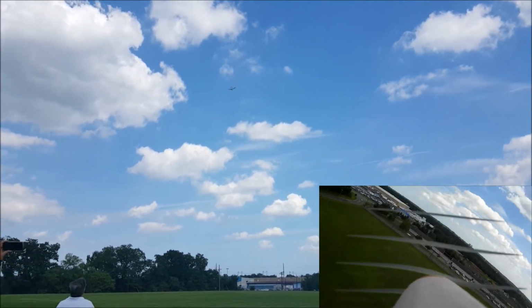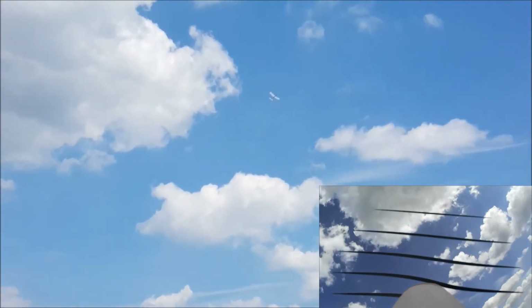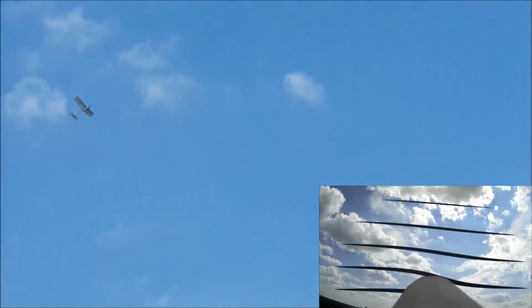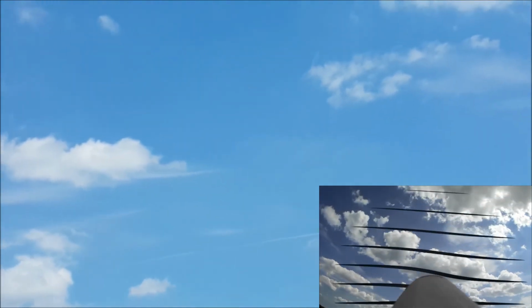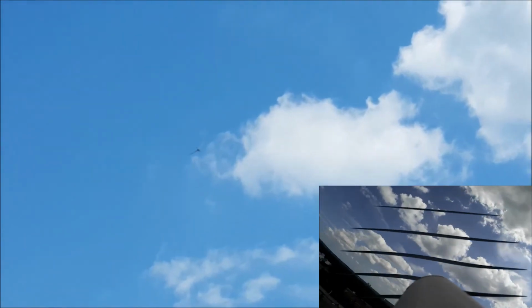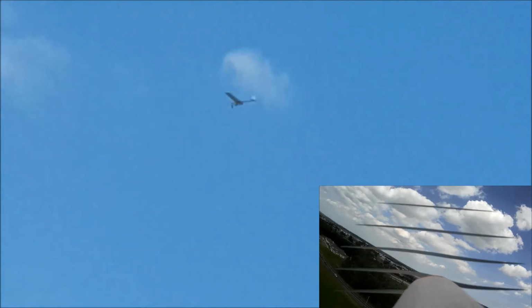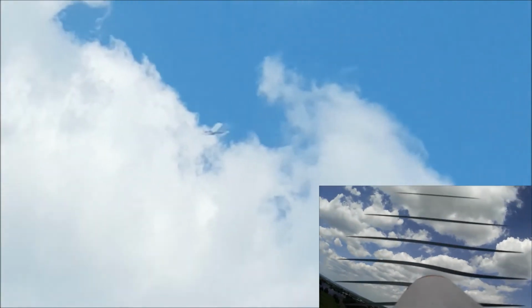Right there you see the plane kind of hover in the air. That's because due to the low wing loading of our plane, we had a very low minimum airspeed. And when the airspeed matched the speed of the wind coming against it, the plane hovered in place for a few seconds. This was a completely controlled maneuver and actually displayed the maneuverability of our plane.